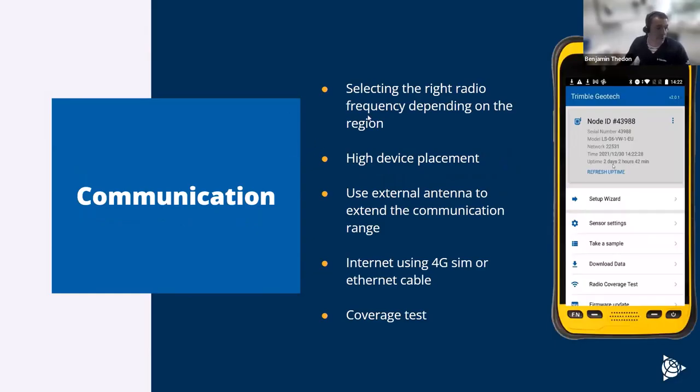And the communication. For geotechnical, you use a long-range radio signal to communicate. So you need to select the right frequency or buy the right gateway, depending on the region where you're located. You need to think about device placement.